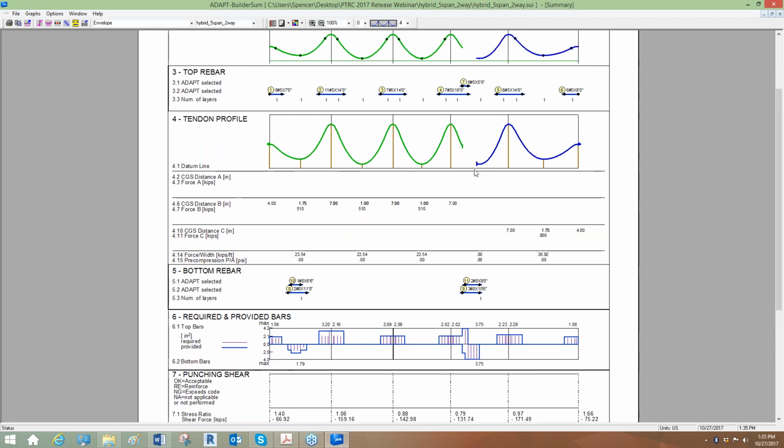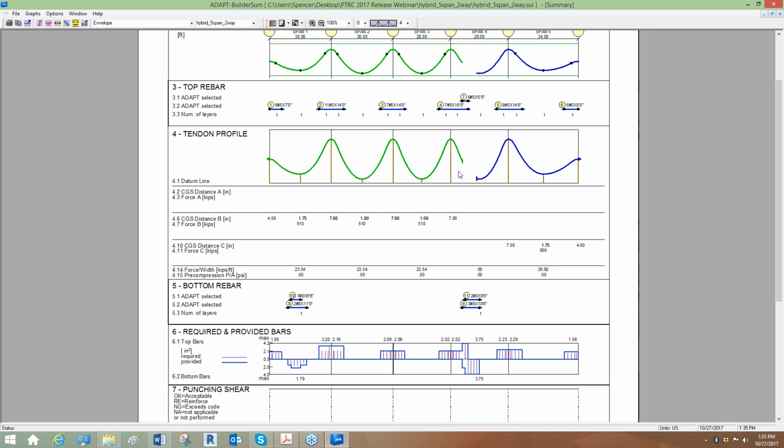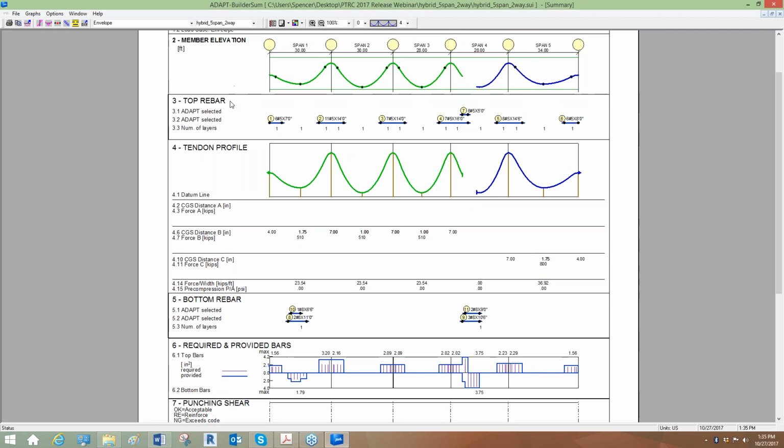We're going to expect a different calculation with respect to minimum reinforcement for the sections within that zone, which, in this case, would be based on just minimum temperature and shrinkage reinforcement, 0.0018 times the gross area of the concrete. And in the previous version, it would have been calculating the reinforcement here from a minimum standpoint based on the stress level.